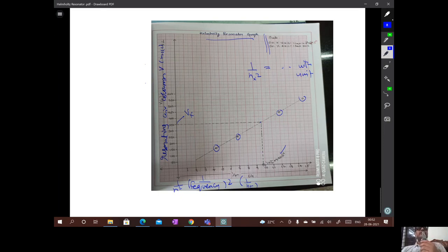When I blow, I am pushing the air past this opening very fast. By Bernoulli's principle, as you know, when I create a flow of fluid with a very high velocity, the pressure there decreases.